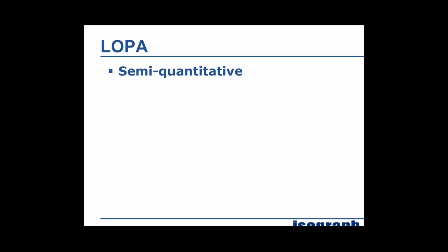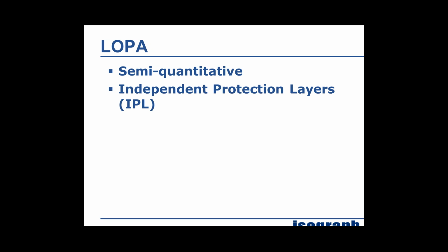Typically, it's more of maybe a HAZOP coupled with some very simple math, like Excel spreadsheet style math, where you just investigate all your different layers of protection and apply some very simple math. Maybe you'd have an engineering team to discuss what layers of protection you have, how they work, and what their probabilities of successfully working are, and then just apply some very simple math to it.